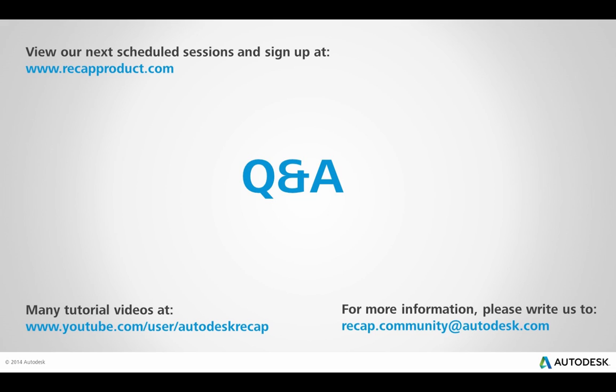Also, you want to make sure that your computer or workstation meets the recommended specifications for Navisworks or for ReCap, for example, especially the video card, because we are dealing with and rendering a lot of points. Yeah, and that's a great point. When you're working with a lot of data, things like your hard drive matter. Even just the difference between a solid state drive versus a typical spinning hard drive can make a huge difference.